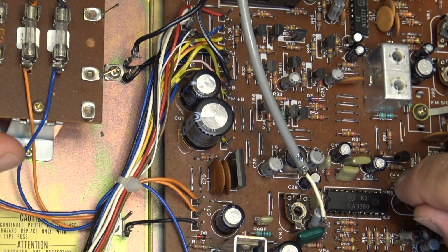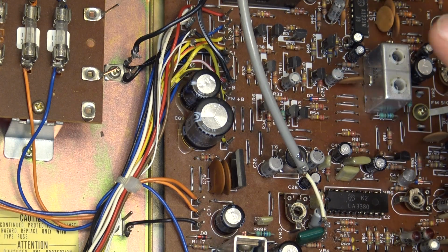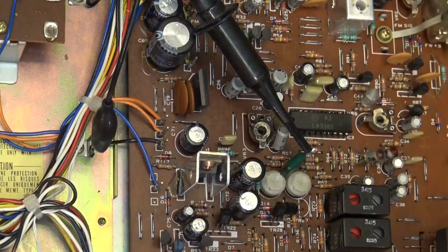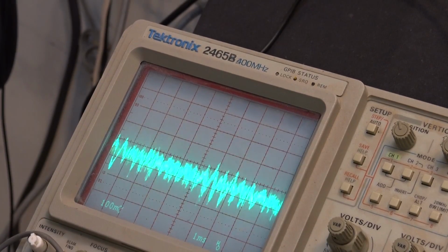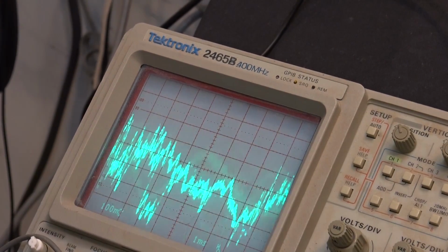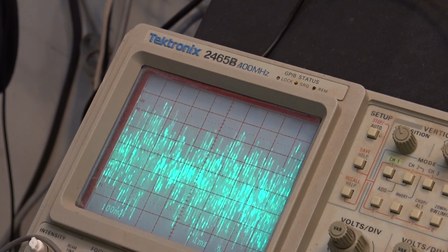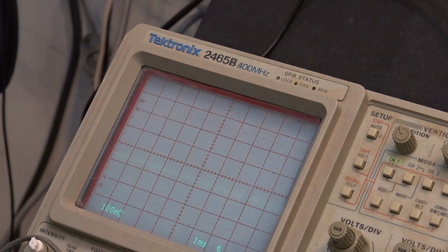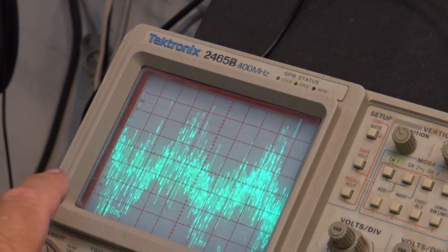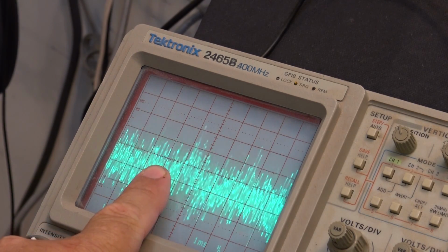I'll turn on the scope here and we'll take a look at what I'm talking about when I mention baseband audio. So I've got my scope clipped to my multiplexed output. Let's take a look at what we're seeing on the scope here. So this is our baseband audio, and this is actually a mono station that we're listening to here, which has no subcarriers on it. I'll tune down to my test transmitter if I can find it. And now you'll notice, you see the extra information here?